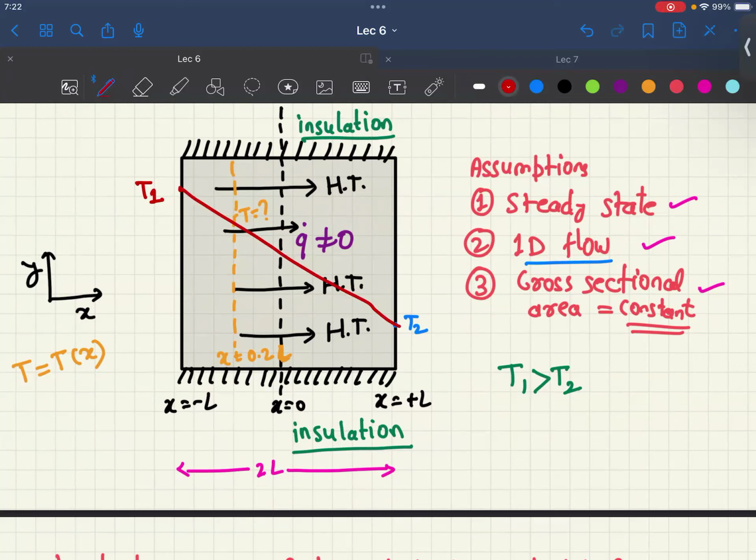But now, since there is a volumetric rate of heat generation, and the second derivative of temperature with respect to the position is constant, we are going to have a curve like this, a maxima. Either it would be like this, or it would be like this, a minima. Okay, so that's going to be quadratic in nature. So without even doing any sort of calculation, we see that this is going to be the case.